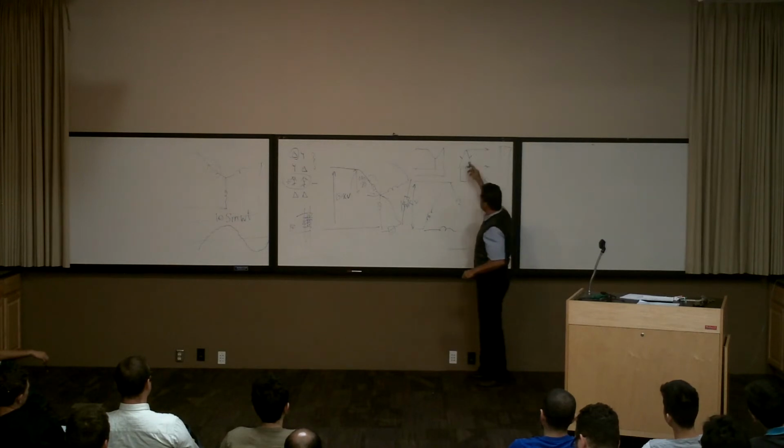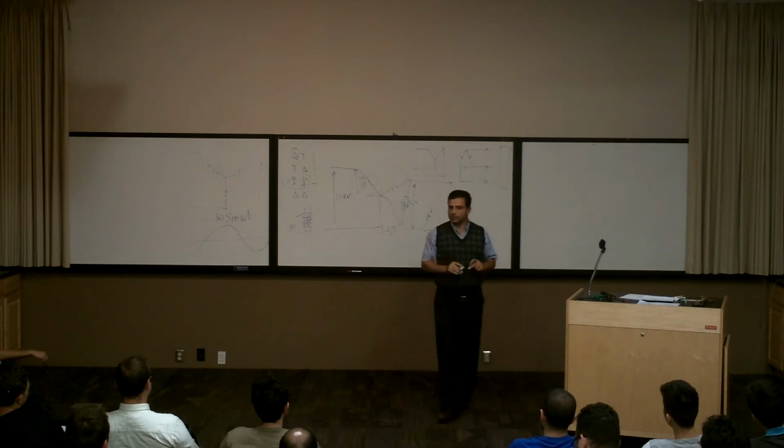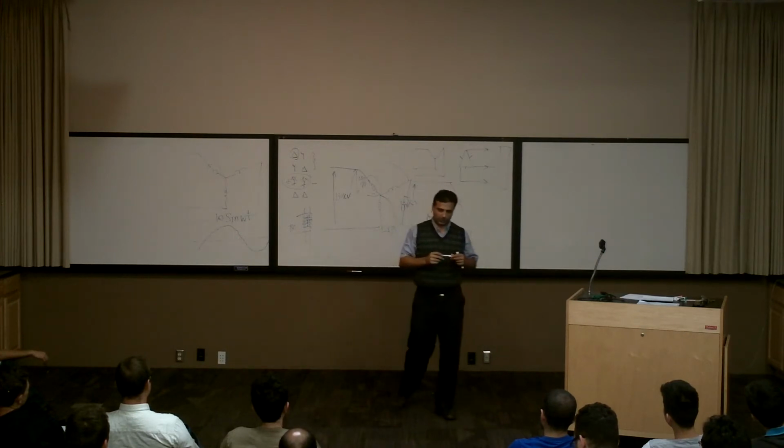And it may saturate the core. Somehow it's good because it balances the load overall when you look at it from this side, but it may cause saturation in the transformer core.